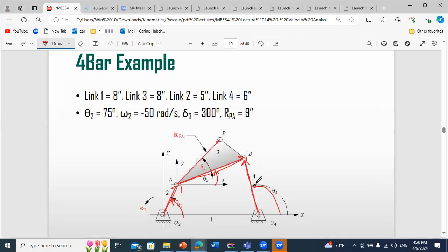If I change, let's say, theta 4. If theta 4, for example, for me is this one, I give you this angle. If I give you this angle, you say, in my expressions, I don't need this angle, I need this one. So if I give you, for example, alpha, you say, I need theta 4. So you do theta 4 is 180 minus alpha, okay? Because when you want to substitute in previous formulas, you need to make sure that all parameters remain the same, okay? So as we said, in this type of problems, we give the lengths of all links.